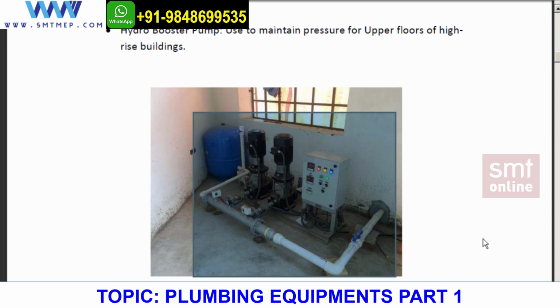So what I'll be doing, I'll be having these boosters over there. What boosters do is, whenever it is being taken care of by the top floors, generally the top 3 floors if it's a high-rise building. Generally a booster pump is designed for the top 3 floors because from the 4th floor down, the gravity force will be so much that it can attain more than enough force for the fixtures to perform in a proper manner.